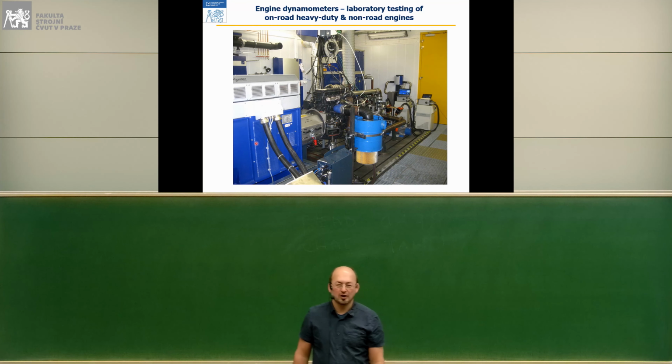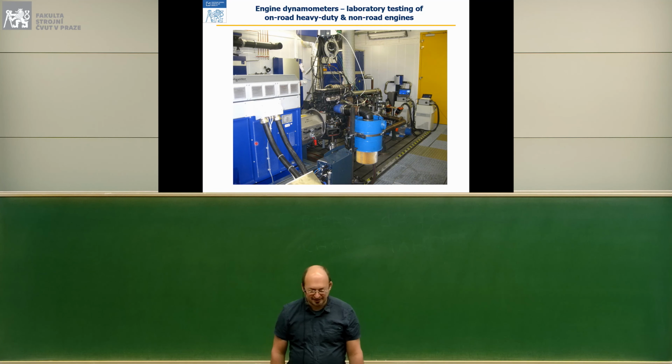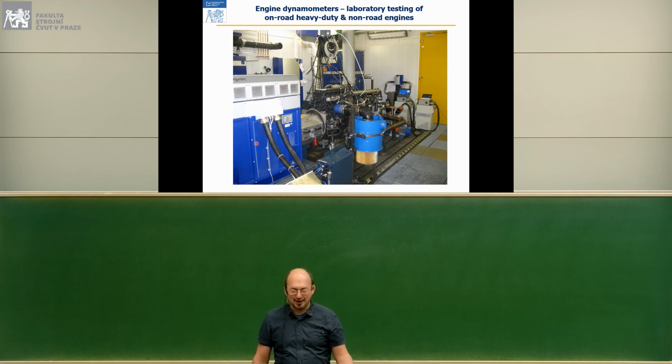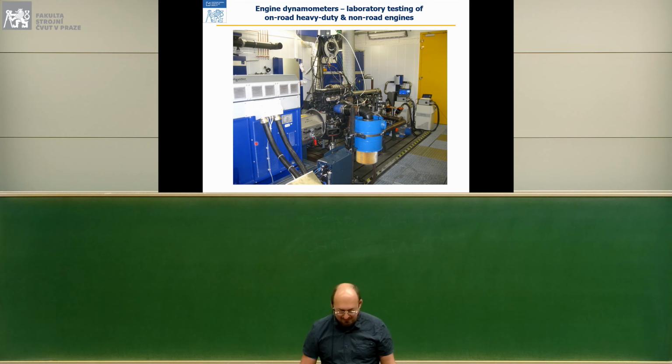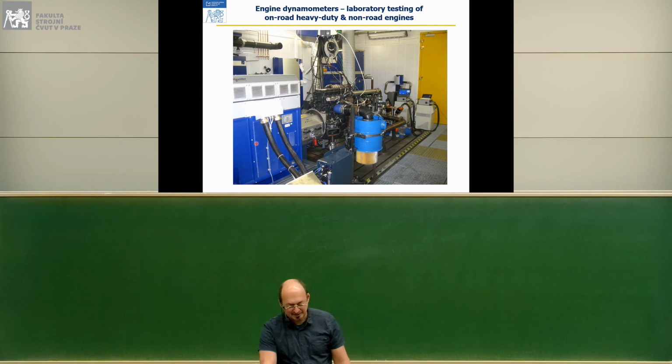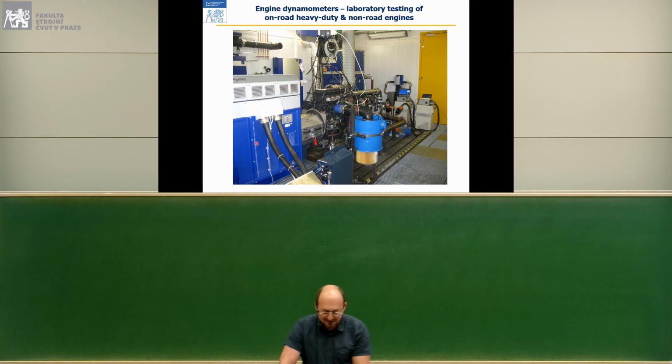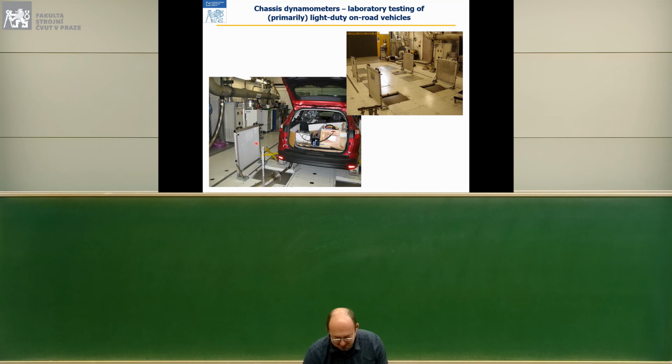This is a 4-quadrant dynamometer, meaning it can turn either direction and it can both absorb power and provide power to the engine. And it's an asynchronous dynamometer, which means it's an asynchronous electric motor coupled with a frequency converter, and that is coupled with the electric distribution grid to which we supply some engine power.